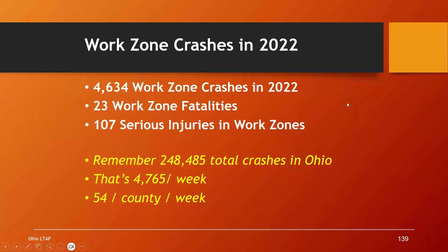If we were to look back at our work zone crash statistics, we'd probably run into a lot of times where the work zone crash could have been avoided if proper advance warning and the proper taper, the proper transition area and the proper buffer space, would have been in place. So we can go a long ways in lowering the number of work zone crashes and the severity of work zone crashes if we do not skimp.